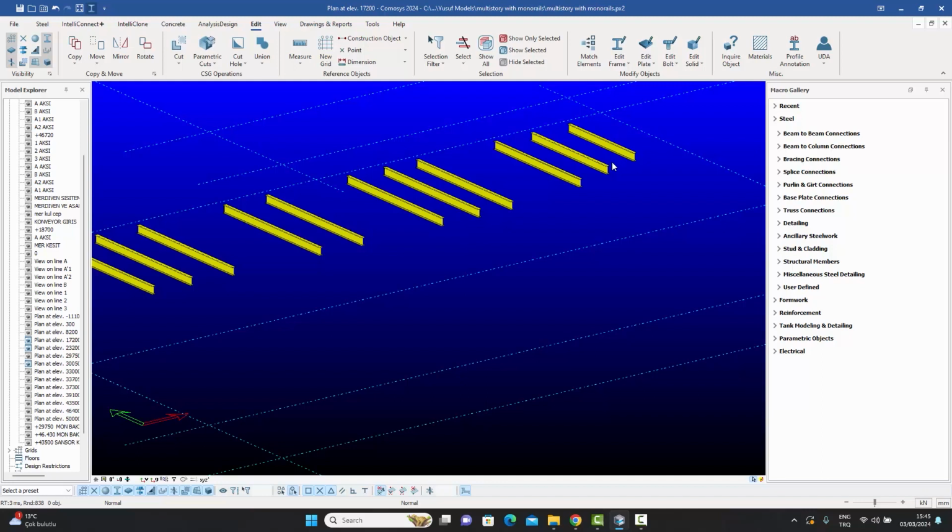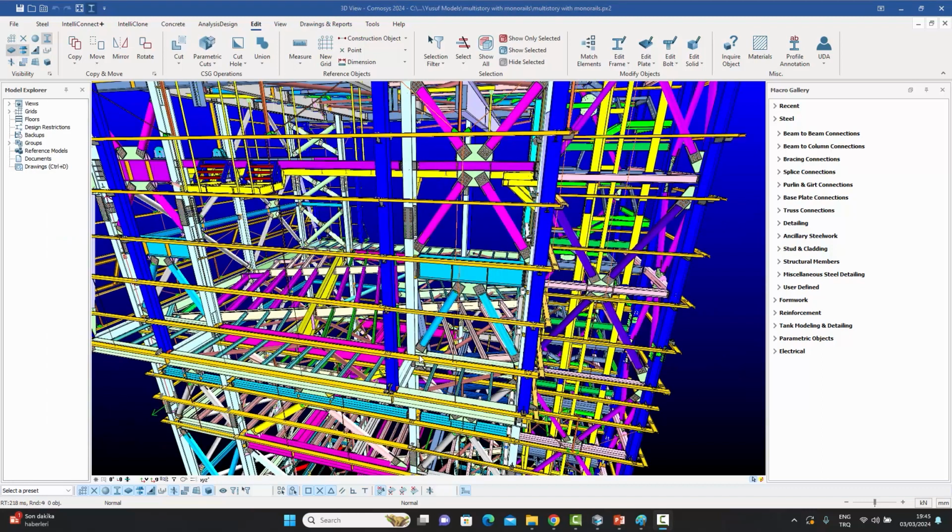And the second area is the custom annotations. So the custom tables and custom annotations. Both in the custom tables, we can use these user-defined attributes, and also in the custom annotations, if you want to annotate these profiles, if you want to annotate certain plates or bolts or rebars in a different way on the drawings, once again, we have the ability to use these user-defined attributes.